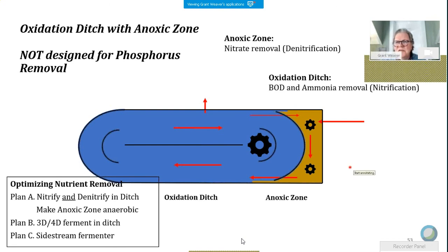If you see that problem, it's a fairly universal problem, and the tools are to look for any place that you get any kind of sludge settling after the aeration zone and eliminate it. Reduce your sludge blankets, and if that isn't it, grab a sample and see if the soluble BOD is low.